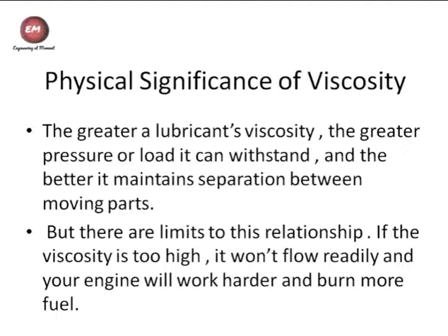In manufacturing industries, when there is an inspection of oils, in most of the cases viscosity is inspected, and when it passes the specification parameters, then only the fluid is okay from the quality control department and it can be used further. So friends, viscosity has a vital role in our engineering applications.